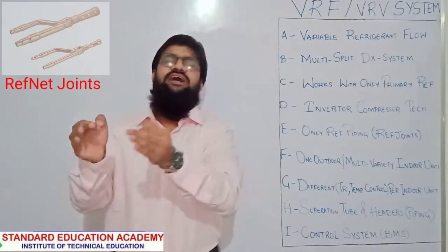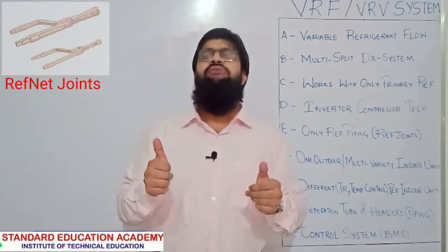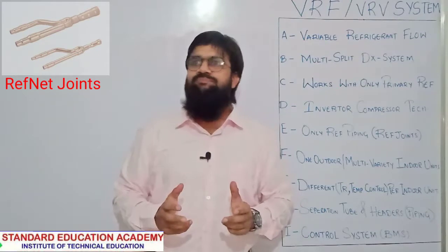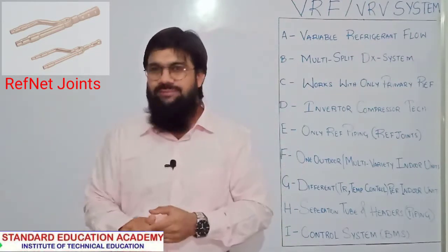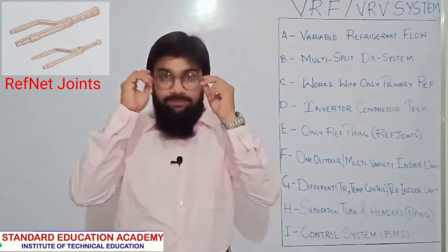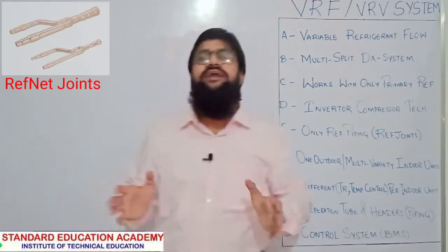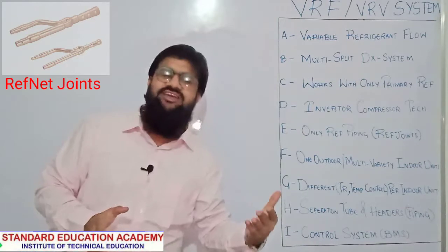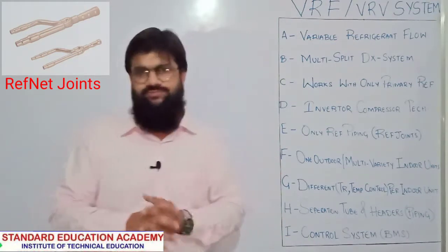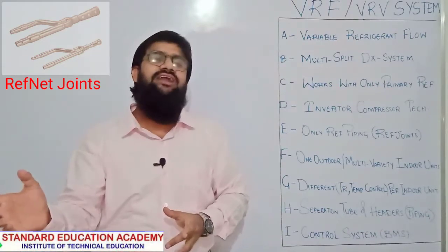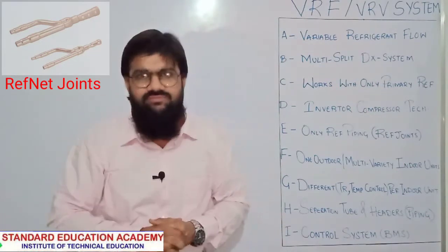in a VRF VRV system. Totally you will be finding piping, and in piping you will have three types of VRF VRV system. Basically, one is cooling type, number two is heat pump VRF, number three is heat recovery VRF. The cooling type VRF and heat pump VRF will basically be two pipe systems, okay, and the heat recovery VRF will be a three pipe system.